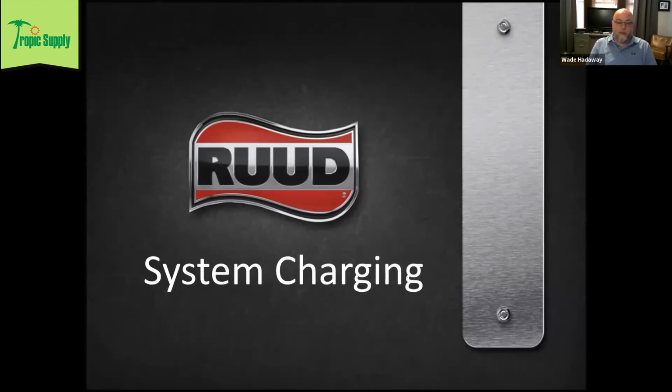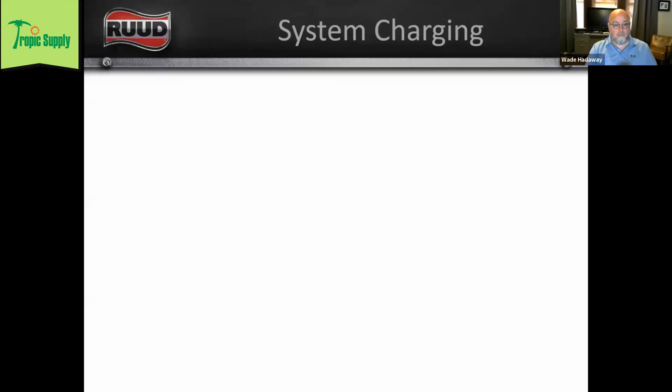It was beat into my brain when I first started doing this, 400 CFM per ton. Well, that's not necessarily the case, right? So we've got to make sure that we know what that rated airflow is, and check it, which will be in class number session 4. We've got to verify that rated airflow, and then we can charge. If we're not moving the right amount of air through our evaporator coil, the charging chart is irrelevant. It's useless. It's not telling us anything.